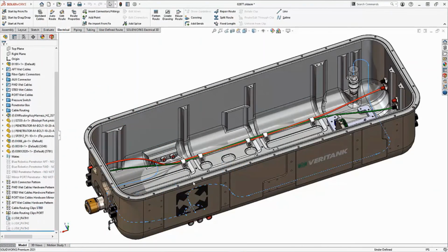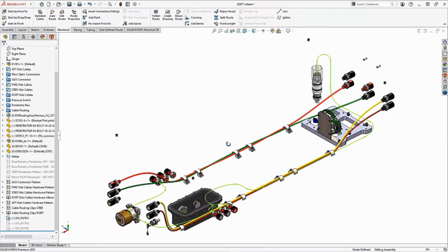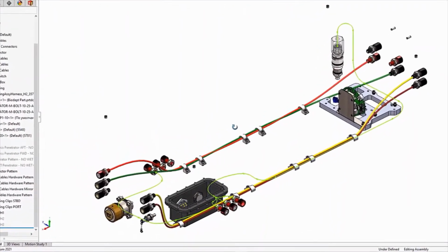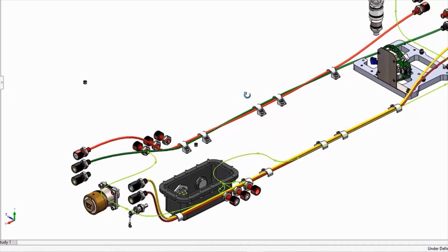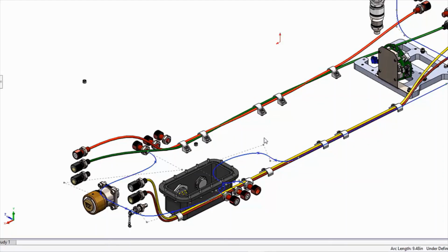We created a routing path using both splines and lines for the harness that connects the transducer to go under already routed cables and follow along the wall. Let's adjust several of the arcs and curves to obtain a smoother path. In the 3D Electrical tab of the Command Manager, choosing Route Harness opens Routing Harness, where you will find new options to route with splines. After routing is finished, the harness followed the predefined path we created.